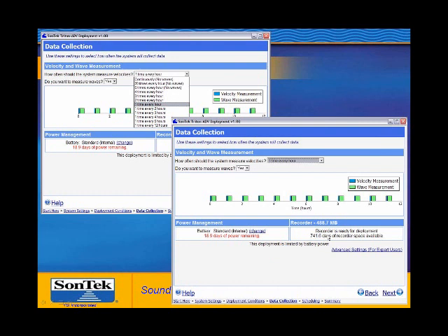We have a question from Jay about the calibration procedures. And Jay, I'm assuming that you're mentioning the compass calibration procedure, as the system itself never needs to be calibrated. The compass calibration is done by, as Matthew suggested, preferably mounting the system in the deployment frame that it will be used in, such that you're compensating for any possible magnetic interference that might be present in the frame itself.